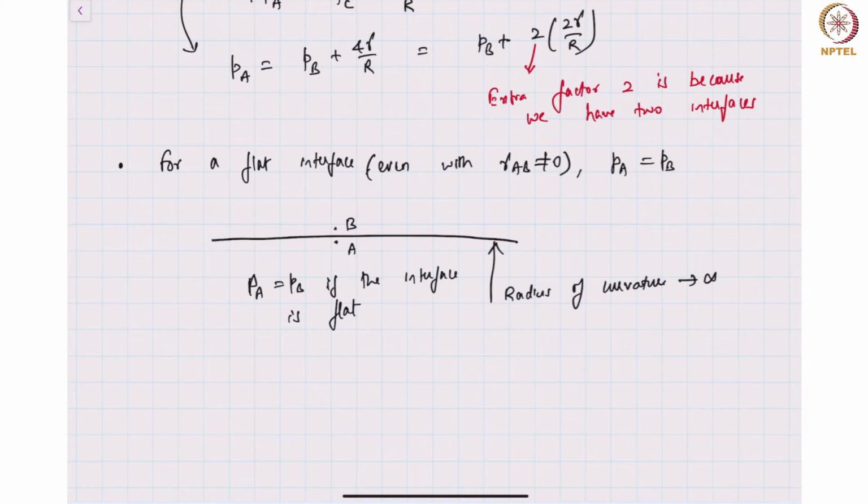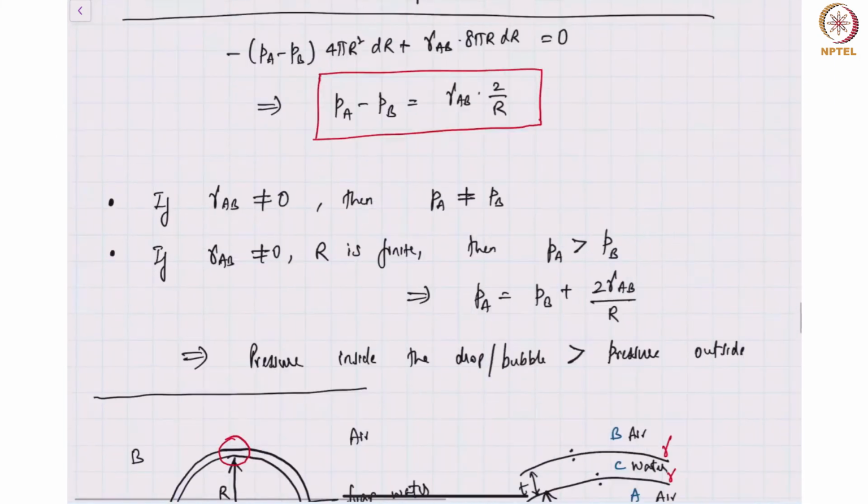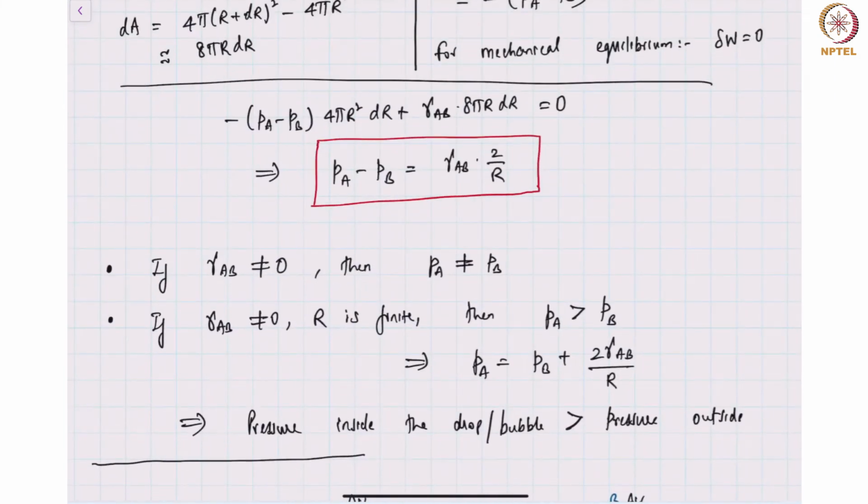So even though I show 2 points on either side of the fluid, we have to assume that these 2 points are very, very close to each other and just across the interface. So there is no appreciable change in the vertical height, when there is gravity. So there is hardly any variation in hydrostatic pressure, because the effect of gravity in this particular statement is negligible. So the statement shown in the box here ignores gravity, because you're looking at cases just across an interface.